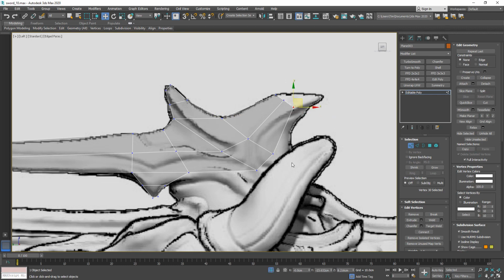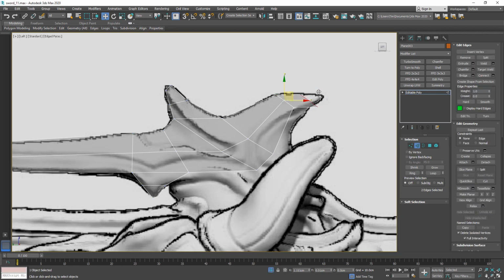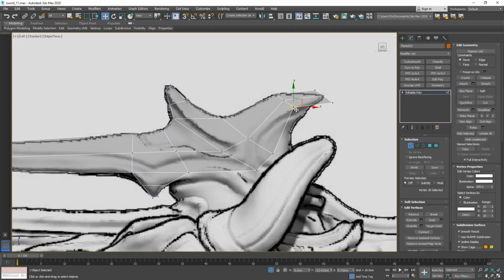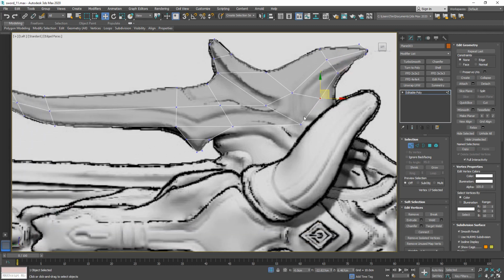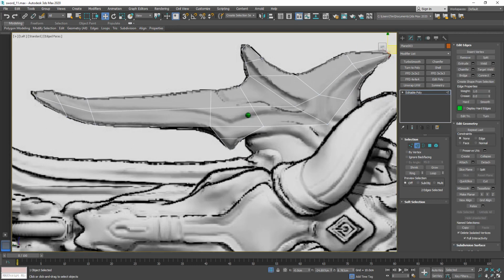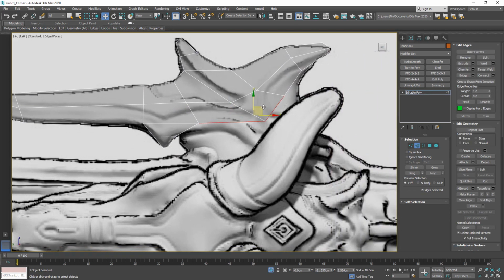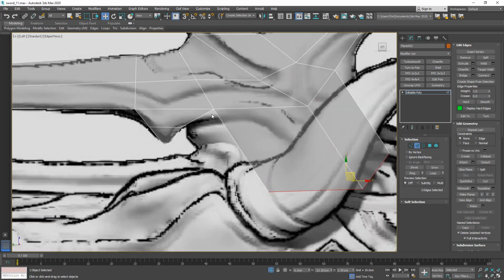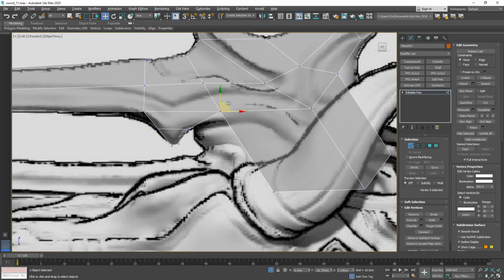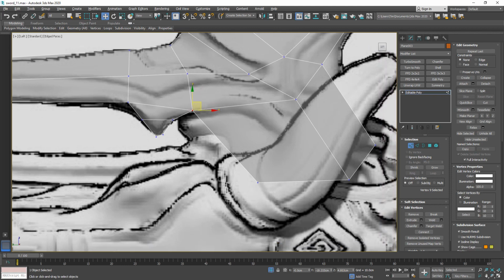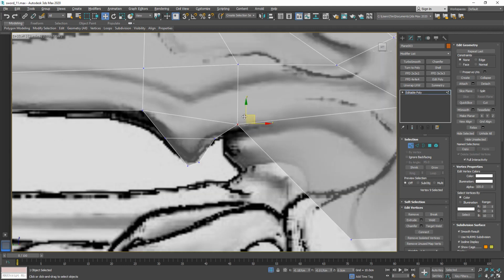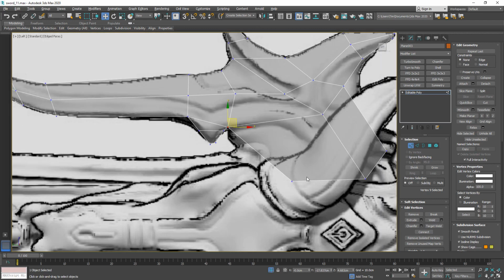And also make sure it follows our concept there in the background to a certain extent. Drag that out here. And vertex mode to shift around a bit here the position of that. And let's go back to edge mode here. Press Control so we have these two edges here selected, and then with Shift we drag out some new faces here. And then it's a lot of jumping around in between vertex and edge mode and really just rearranging.